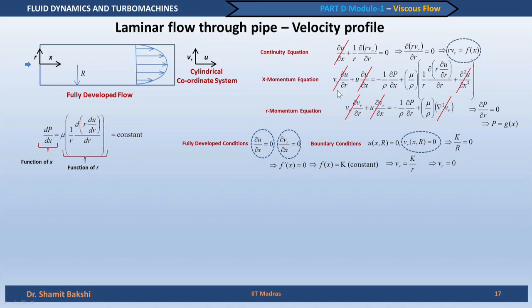and this is of course true for laminar flow, because for turbulent flows you cannot drop out the unsteady term, because turbulent flow is highly unsteady. So, we cannot drop out the unsteady term. Okay, so for a laminar flow we get that pressure falls linearly along the direction of the flow. In the plot in the last slide we had utilized this to get the pipe pressure loss in the entrance region. Now, we have proved it using the Navier-Stokes equation. That is what it says, the pressure drop in the developed region is linear for a laminar flow.